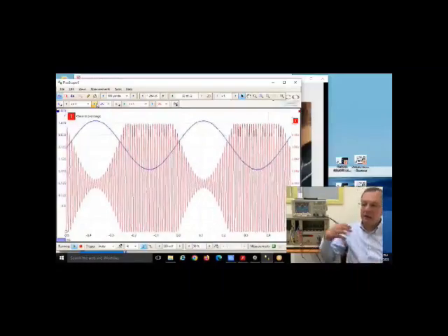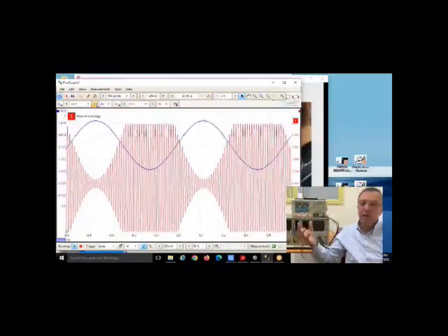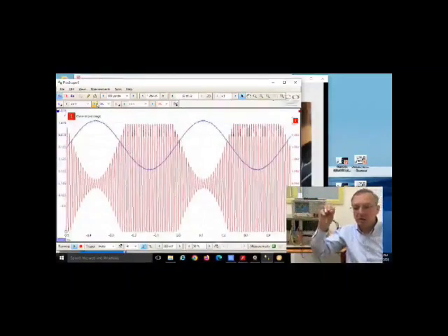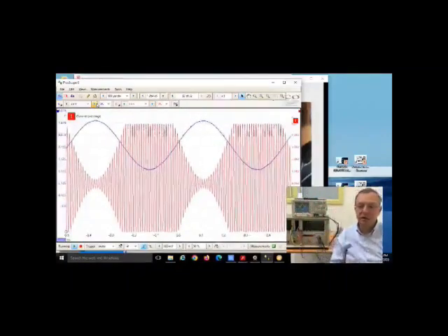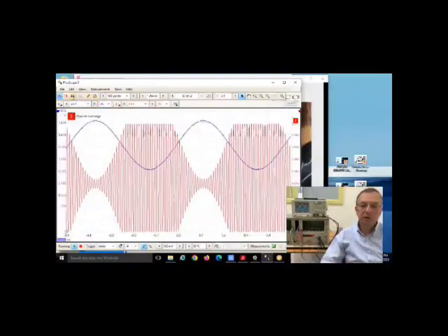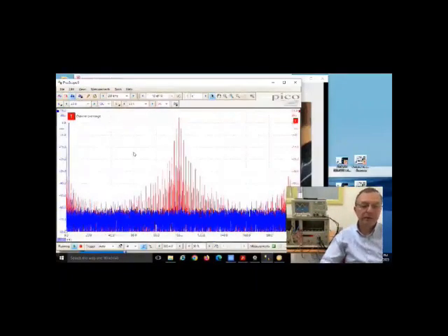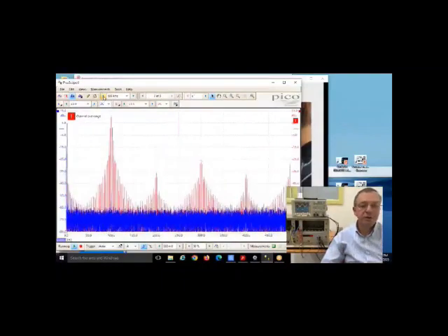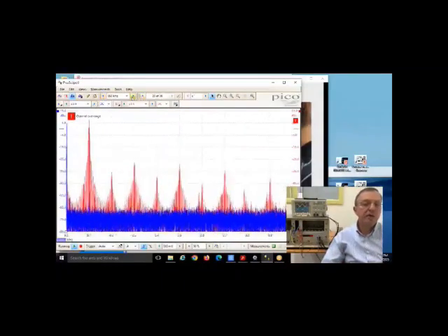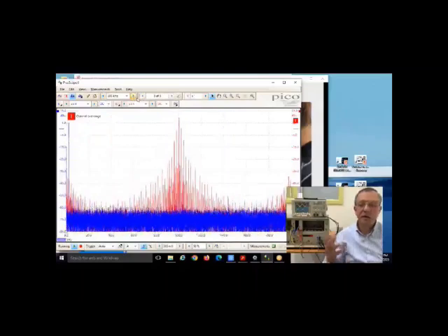Why in the mobile phone network, why do the base stations, why do the signals have to be adjusted to make sure there isn't clipping? Well, let's look at the spectrum. Aha, you see, what does clipping produce? Clipping produces a lot of harmonics and a lot of noise. So here is a very simple demonstration, even using old-fashioned AM, to show why clipping is bad.